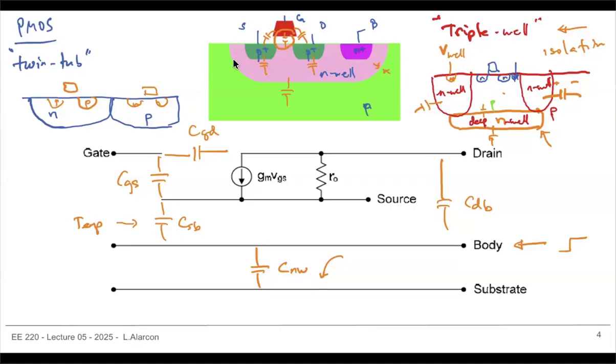And if they're meant for isolation, then you want to make sure that they're all reverse biased, so you don't have much of a current flowing. Again, you will have leakage currents and so on, but in most cases, those are orders of magnitude smaller than your actual current. And at the same time, if you maintain very little voltage, then the actual leakage power is small. Okay, good. So any questions here?